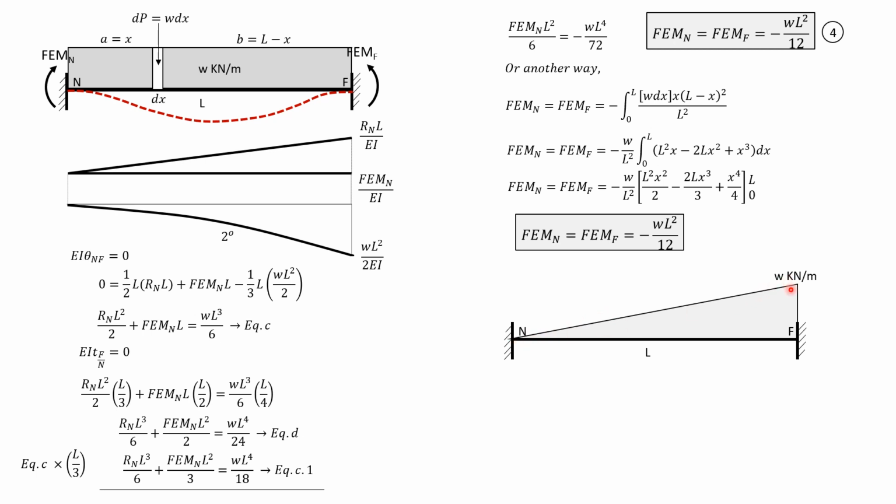Now, for this triangular loading, we do the same thing. We consider a strip. You can also derive the formulas by the same approach here by area moment. So we draw the moment diagram by parts if you want. But let's just use the result for fixed moment of a concentrated load because it's faster and we don't need to draw a moment diagram. So we have here dp, which is equal to height of strip, which is y dx.